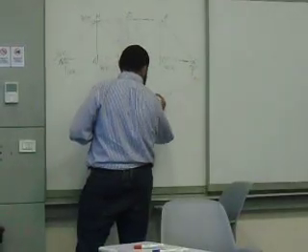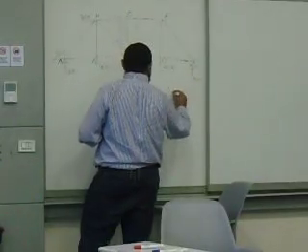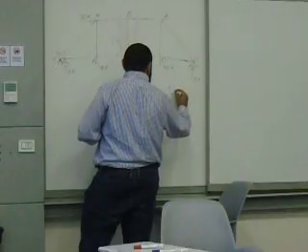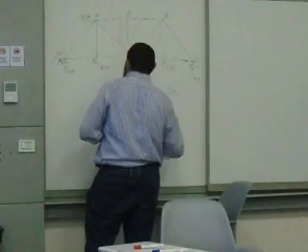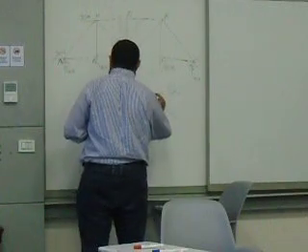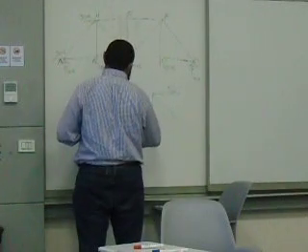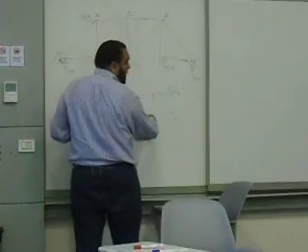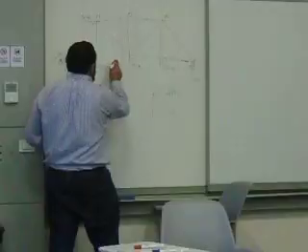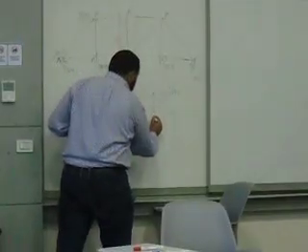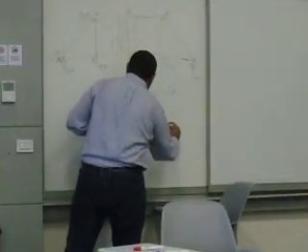And here this is called FHG. And here I'll have another force called FHC. And here, this is not an unknown because I didn't do a cut in the vertical. But I need a cut in this horizontal. So I have FBC.